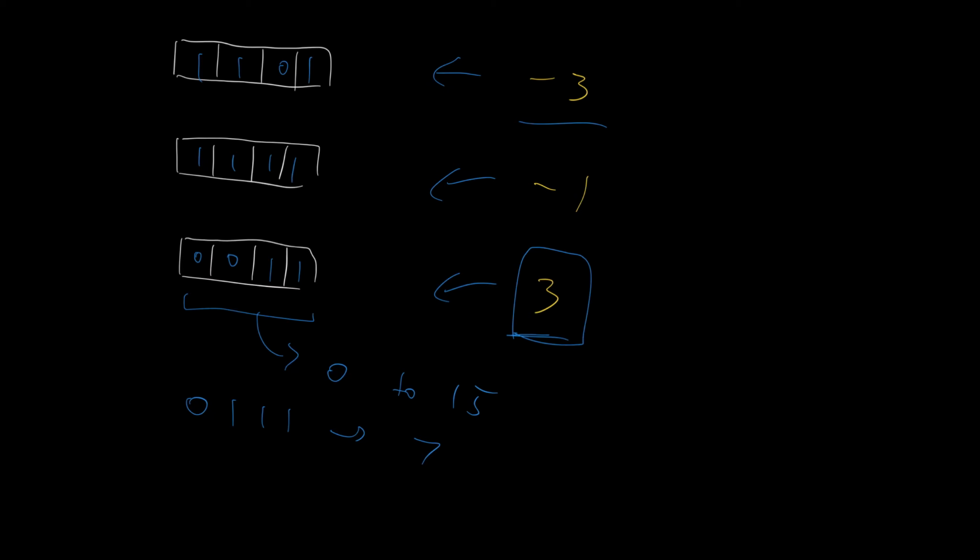That's what needs to understand that when we have certain bits in certain registers, then us humans want to interpret them as corresponding to these numbers, and if we ask Verilog to add these 2 numbers together, then it's Verilog and Quartus that has to figure out that if this has got this bit pattern in it, then this number is -3.